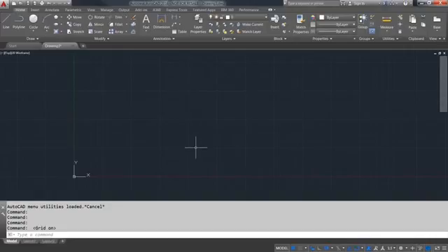So to sum up and wrap up the question, there really isn't a command for the startup wizard per se, but if you change the startup variable to a value of 1 and you start a new drawing at that point, then you'll have the option to choose the wizard to go into. Hope that helps.